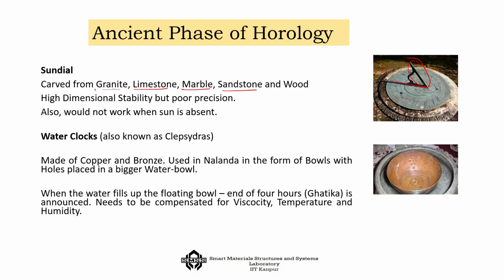And of course, another important thing you have to keep in mind is that whatever you are going to use in the heat should not thermally deform much. So, it should have high dimensional stability, which almost all of these stones have, as they are either metamorphic stone or igneous stone. So, they can withstand the high temperature. Also, you keep in mind that this system would not work when there is no sun.